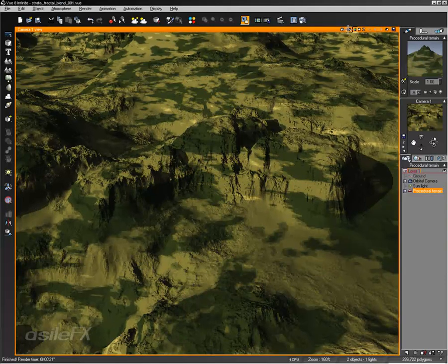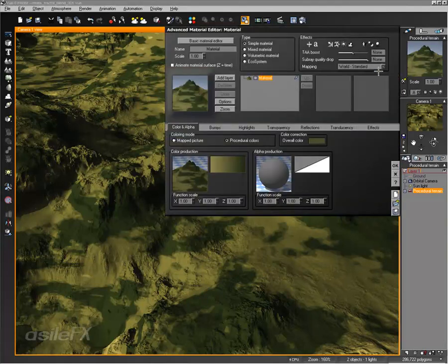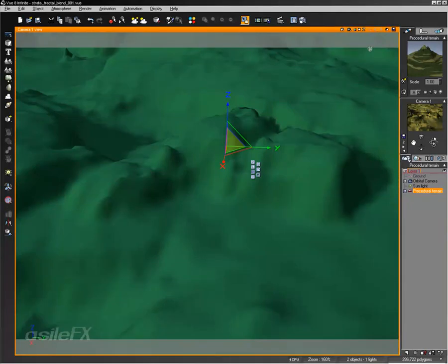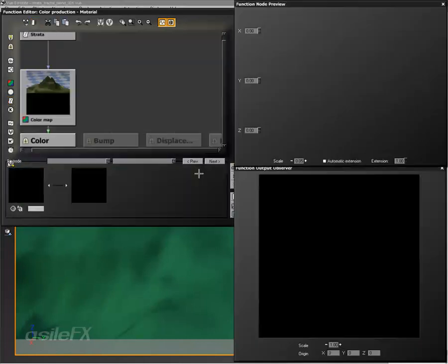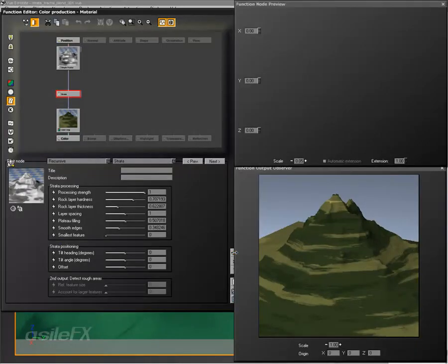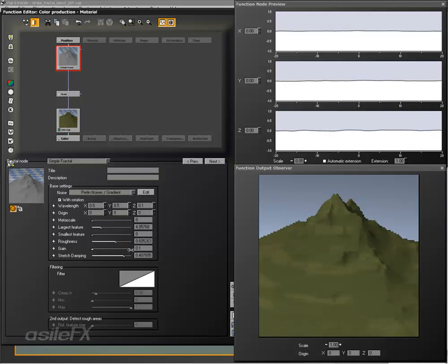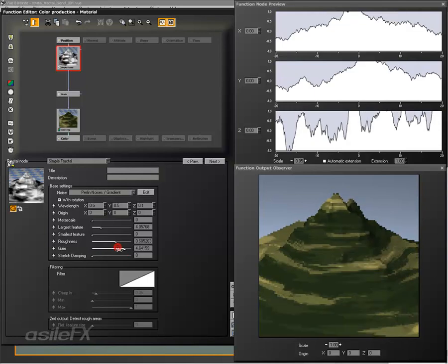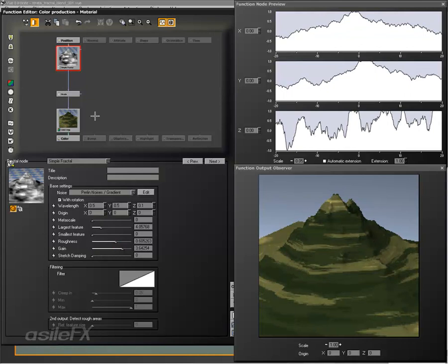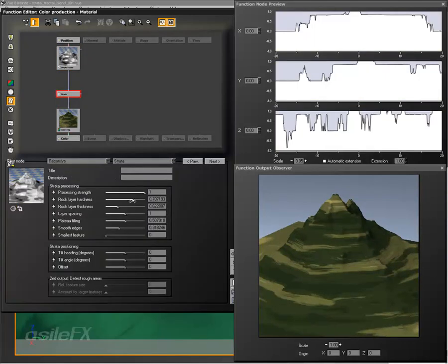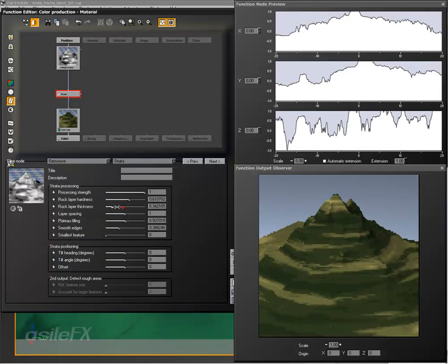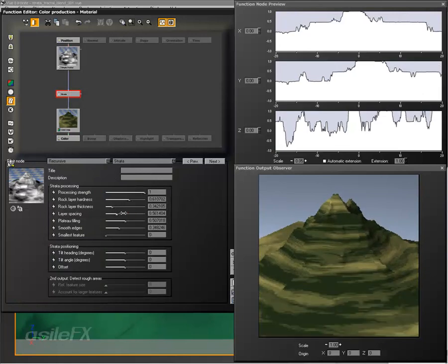The look will also change between mapping modes. So if we switch this over to, let's say, World Parametric, now this is going to reduce the overall scale of the material. And it looks like we have a little bit too much green, so I am going to just modify the gain. And then we can go back into the strata and change maybe the thickness and layer spacing.